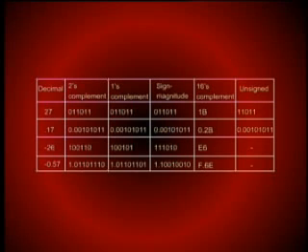Now there is no unsigned representation for this example. For negative numbers, you can't represent negative numbers in unsigned. And correspondingly, for 16's complement represented in hexadecimal, it is E6. So you could just consider it as, in hex, 100 minus 26, that would be actually E6. The fraction minus 0.57 is in this case, in 2's complement, 1 point the remaining part, meaning that now this would be a fraction in 2's complement.